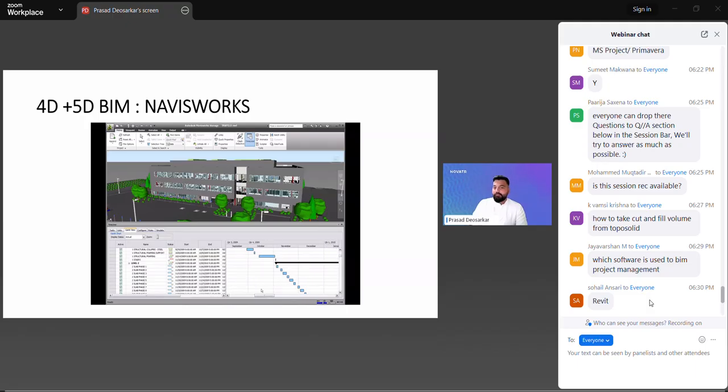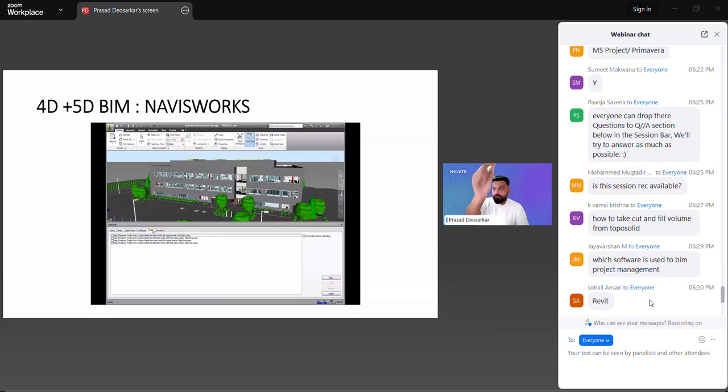Okay, so once you have imported the schedule, you can also do a plan versus actual comparison in the BIM software itself, where it will show you two different Gantt charts based on the dates. Okay, like you see on the screen. And then from there on, you would also be linking each of these particular activities to the BIM elements or the BIM models. Okay, so now you see that you have created the configuration, you have created all the tasks.